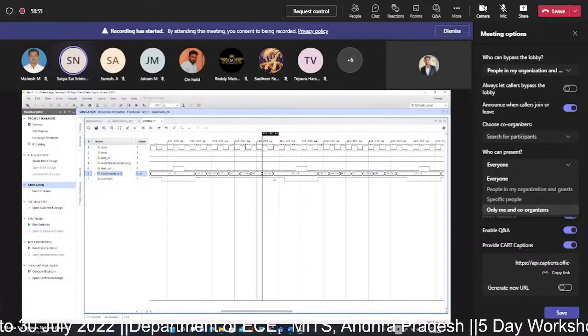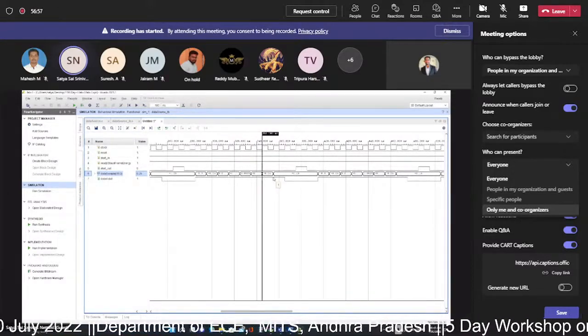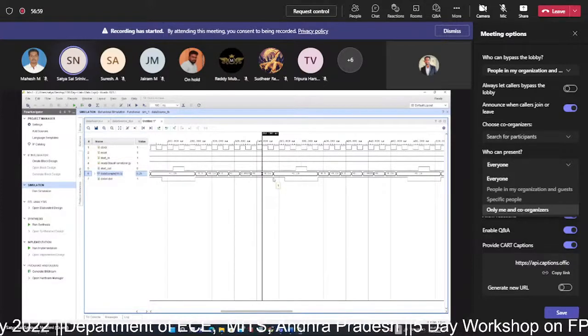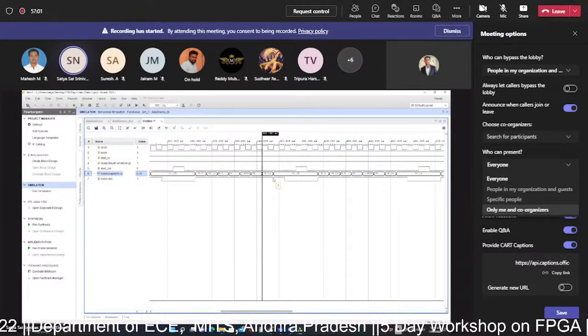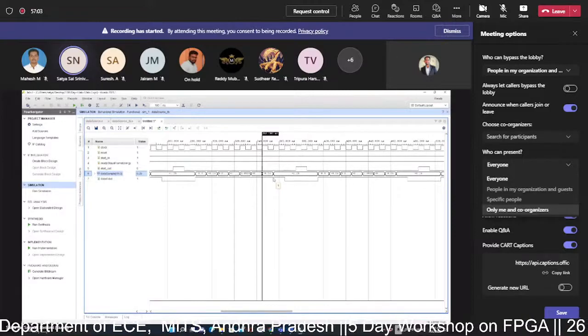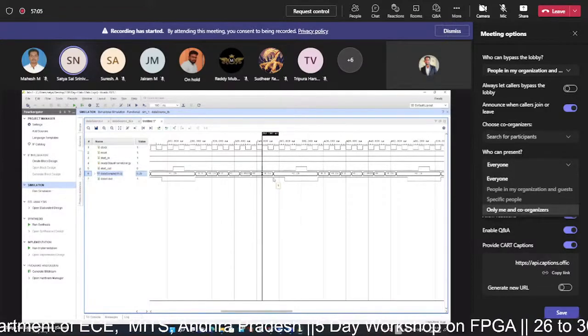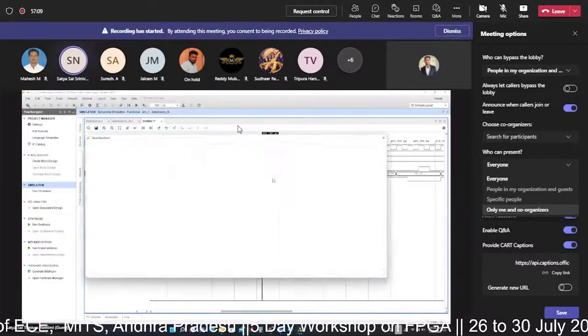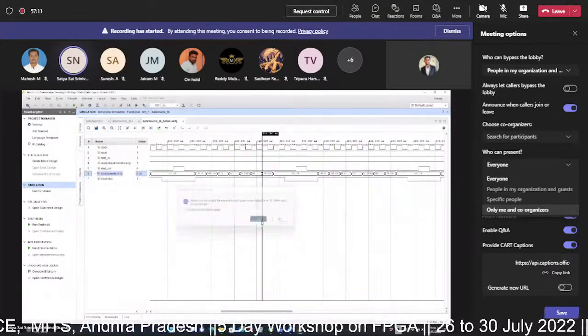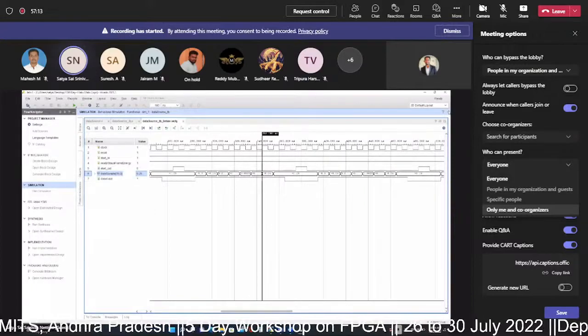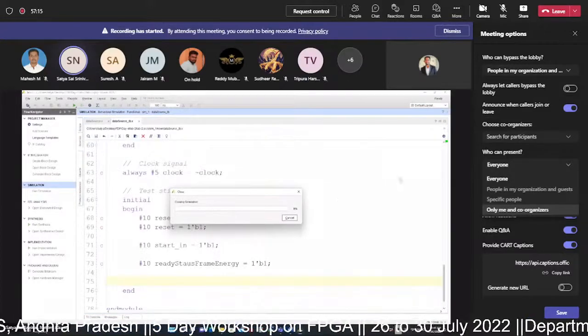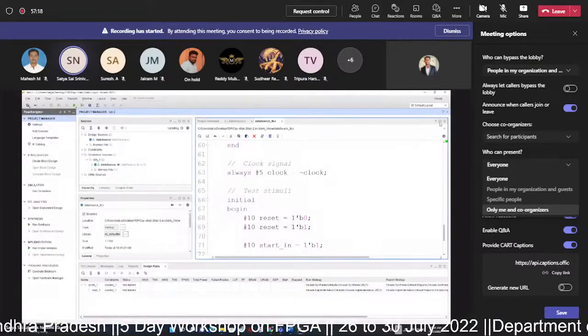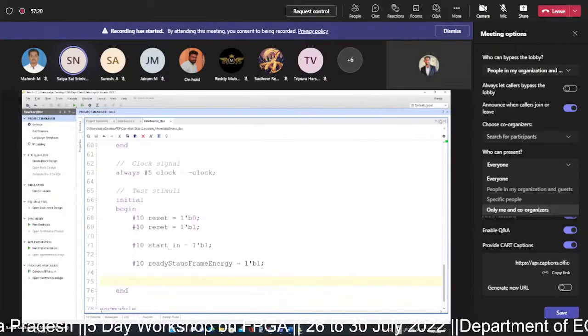Now we can perform the block level design, wherein this data source can be integrated with the frame energy module that we designed earlier, and then implement it on FPGA. Since the simulation has passed, let me check whether we are able to synthesize it and get a gate level netlist, or RTL equivalent netlist, for this description.